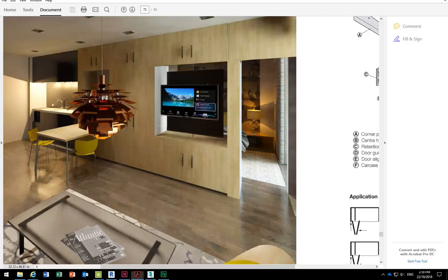So even though you might make most of the unit just using model in place, you could still make things like the door handles as a loadable family, and that way if you change one, they'll all change. And there'll be lots of elements like that, even in your built-ins. But then when you've got lampshades, chairs even, definitely tables, you can maybe start to think about using loadable families a bit more.